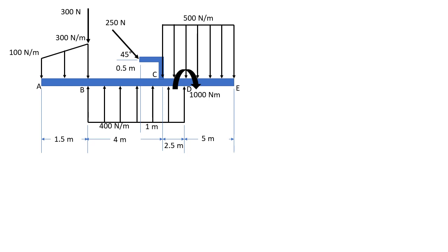Okay, now this is our beam and we will draw the free body diagram of our beam. At first, I labeled the points A, B, C, D, and E. These are our change of load points. To label the support reactions, we have a fixed support at E, so we would put a force along X, a force along Y, and we will assume a counterclockwise moment ME.